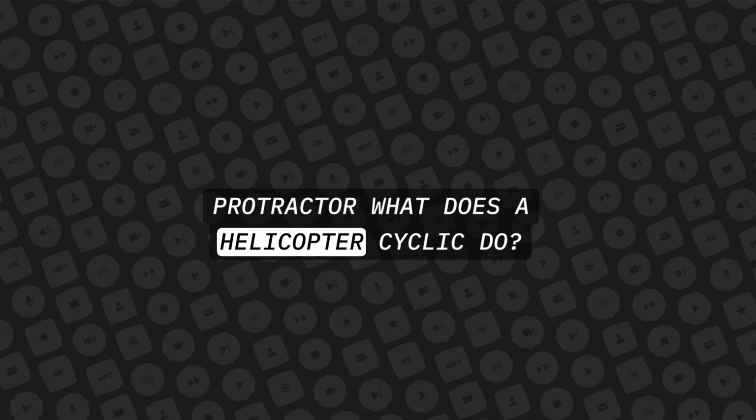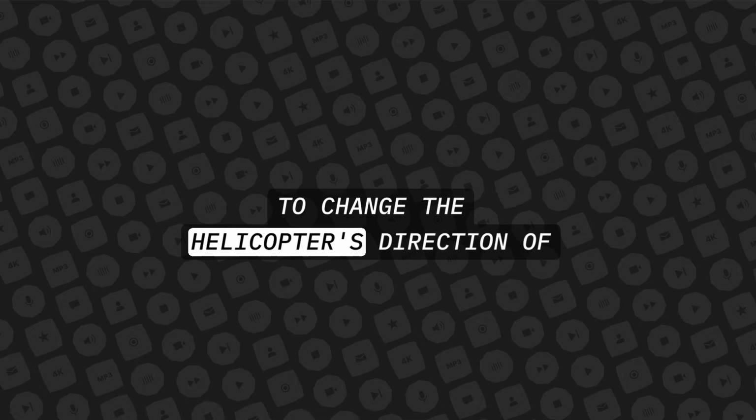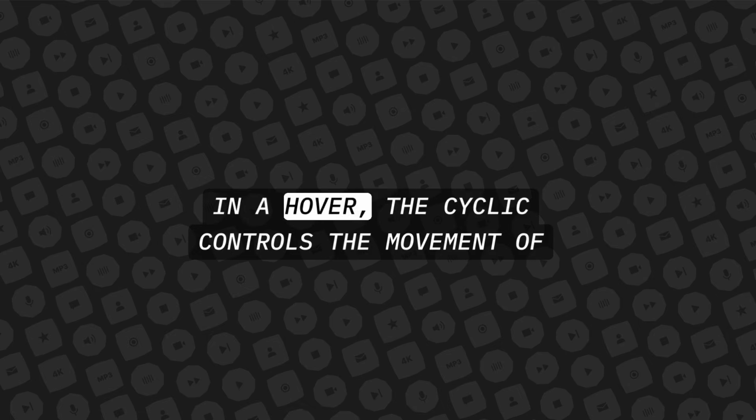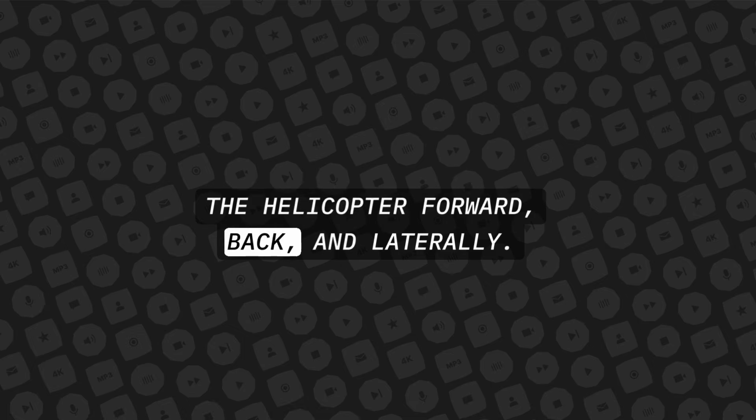What does a helicopter cyclic do? The cyclic is used to control the main rotor to change the helicopter's direction of movement. In a hover, the cyclic controls the movement of the helicopter forward, back, and laterally.